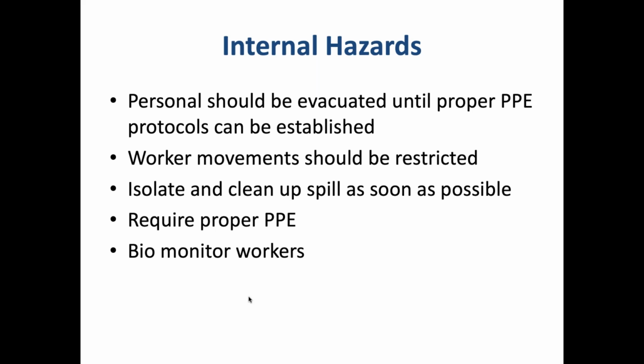You want to isolate and clean up. If it's a spill or a release, you want to clean it up as quickly as possible. Before you do that, you want to evacuate the area. Make sure you have a proper protocol for protecting workers that are going to do the cleanup. And you're going to be required to measure the worker's exposure using various kinds of monitors, the various kinds of monitors we were talking about before.